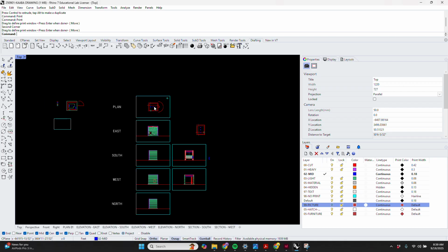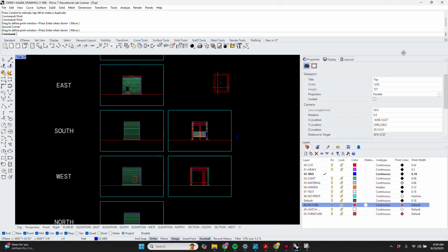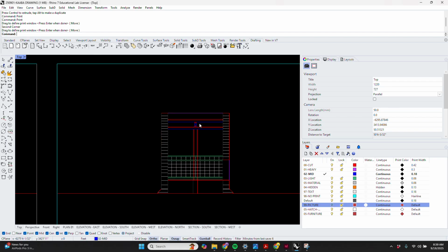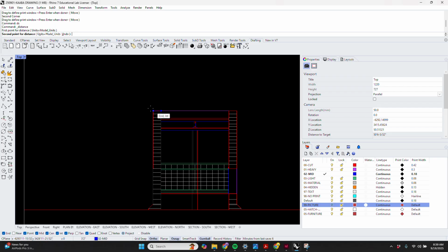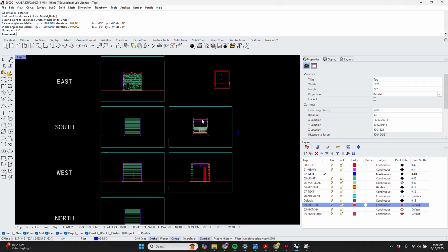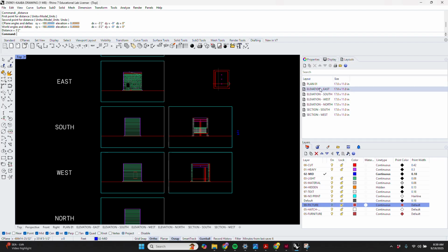The advantage of having stuff set up as layouts, which is what I've already done here. So here we're in the model space, where if I was to measure something, that distance is 3, 2. So that's the actual distance of that wall in the building in the real world. And so layouts work a little bit differently. Layouts are scaled to the size of the paper. So here, when we see this black background, that is my assigned background for model space.